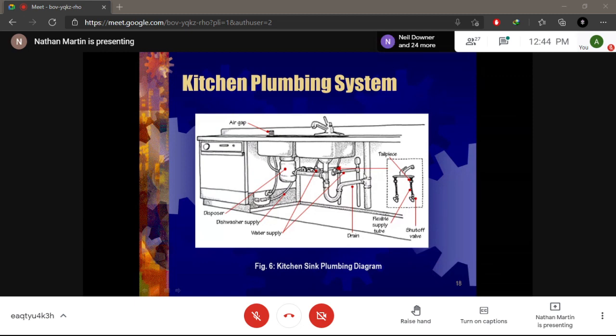That is to allow flexing of the joints to relieve strain. So you don't want a lot of strain on these joints. A lot of strain on the joints will cause leaking, right? So you want the transition to be smooth, right? Because there's no thread tape here, no PVC cement here. It's just a plastic washer here, and a plastic washer here, right? And remember, this system doesn't keep any pressure, right? Because of the vent pipe.